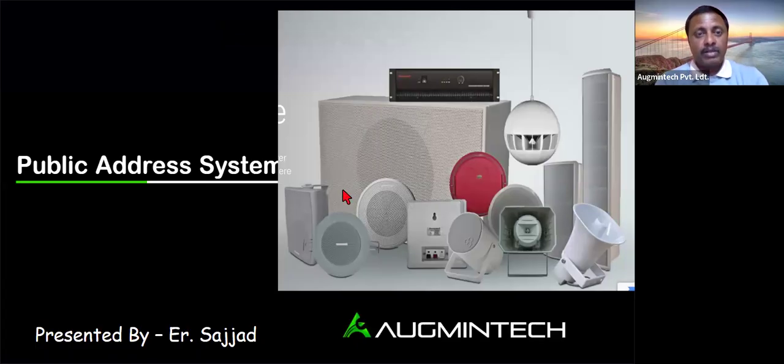I hope you have done fire alarms also, since in your firefighting system you would have studied fire alarm systems. Fire alarm is just the detectors and a fire alarm panel. Detectors means smoke detectors, heat detectors, and carbon monoxide detectors. For taller places like atriums or assembly areas, we use beam detectors. In the case of ducts, we use duct detectors. And the notification devices we have are sounders, horns, buzzers, flashers, etc.